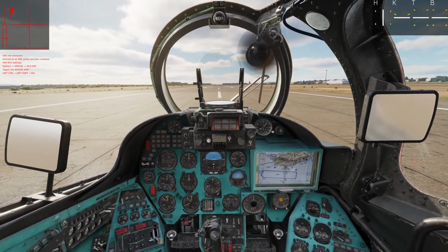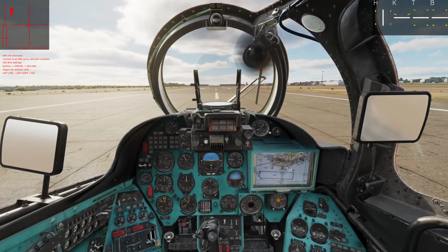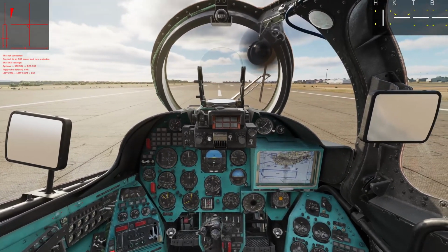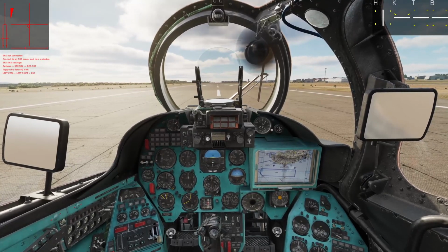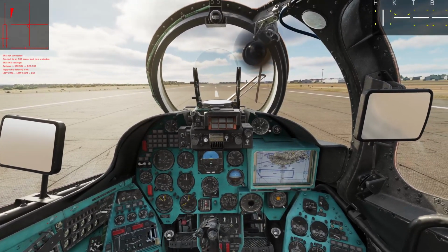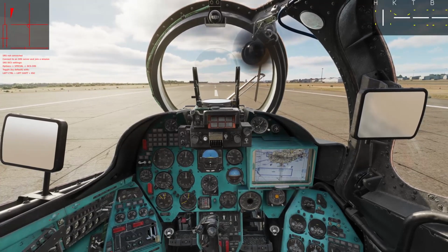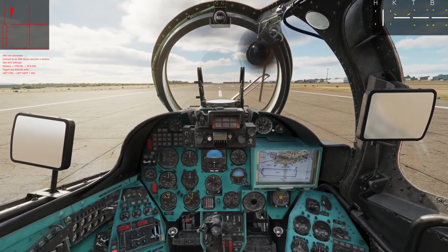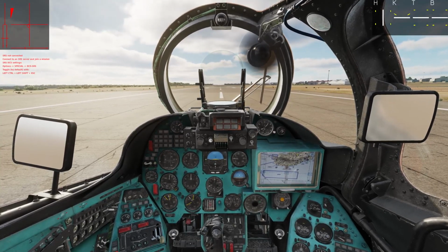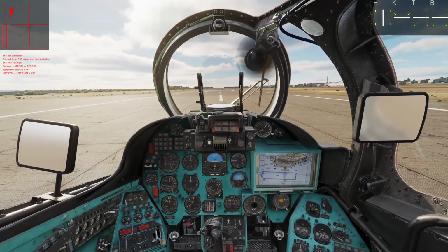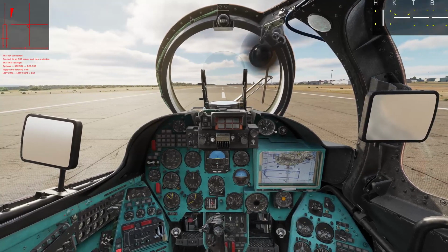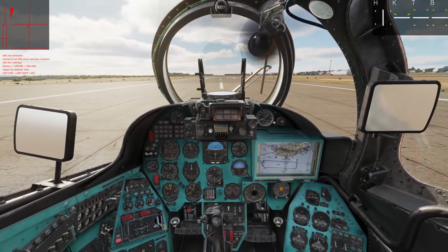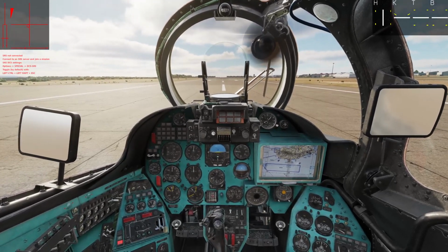In right side flight, going the other way, you're putting the tail rotor in a descent condition, and you could potentially enter a vortex ring state. And I'm seeing some issues there with the flight model. However, those issues are not necessarily consistent with a tail rotor entering VRS. I think something else is weird.